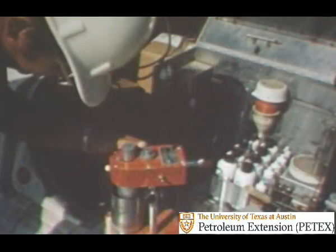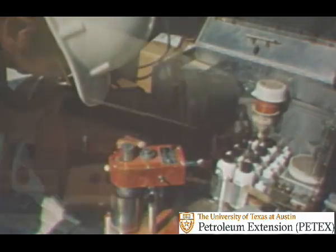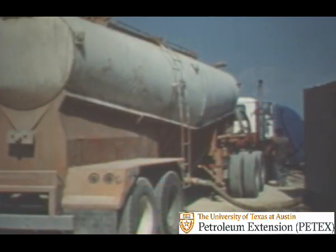The mud engineer tests the viscosity and other properties of the water-based mud still in the hole. The water-based mud must be in good condition before it is removed and replaced, that is, displaced out of the hole. Its being in good condition assures better displacement. The tank truck carrying the oil mud from the mixing plant arrives at the rig. The mud is put into the pits through a hose after the water-based mud is emptied out of the pits.